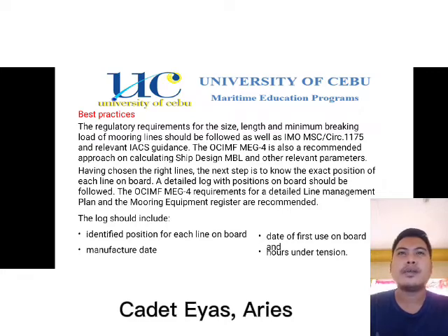Having chosen the right lines, the next step is to know the exact position of each line on board. A detailed log with position on board should be followed. The OCIMF MEG 4 requirements for a detailed line management plan and a mooring equipment register are recommended.